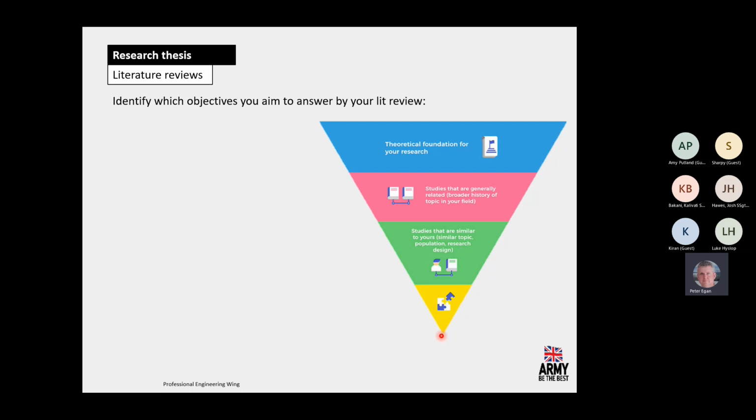So something could be really sustainable in the UK but may not be sustainable at all because of where we put it in the world and the supply chain it's taken to get it there. It could be the most sustainable modular building in the world, built and used in the UK. But when I've shipped it around Africa, moved it across Africa and flown it 200 miles, it's no longer sustainable, because the embodied carbon in that transport is going to take 60 years to repay. And it's only got a 20-year lifespan.